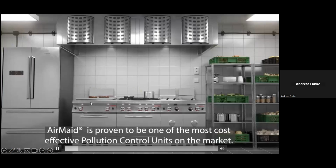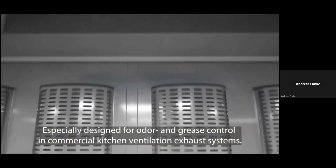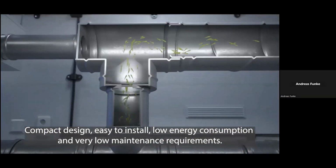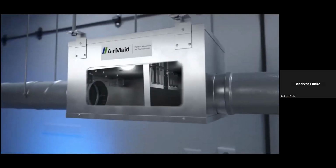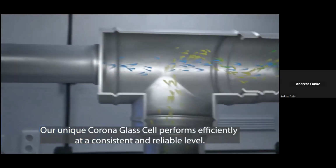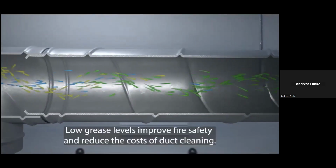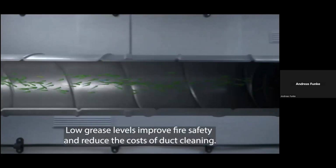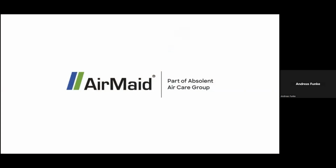I'm showing you this small video here again to summarize how this principle works. So the dirty air is coming into the main duct, and ozone will be added here through this small unit. You can see here the corona lighting, the air is passing, and ozone is created and bled into the main duct, and then by time, during these minimum 3 seconds, the grease particles will be destructed, and the relatively odor-free air will be released.